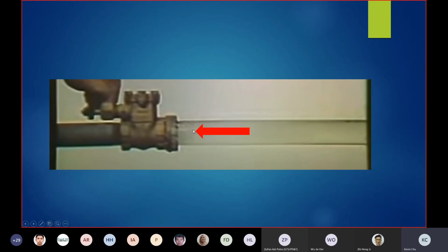If the liquid has very high inertia, the smashing against the valve can be very catastrophic to the liquid system. After that, the water will move back and forth, repeatedly smashing against the valve until all its momentum is lost. That is how the water hammer behaves when you suddenly shut the valve.